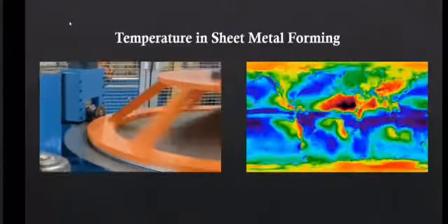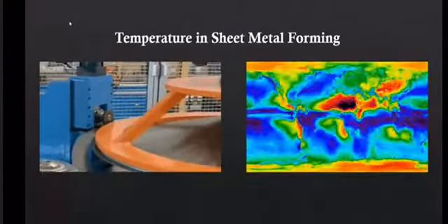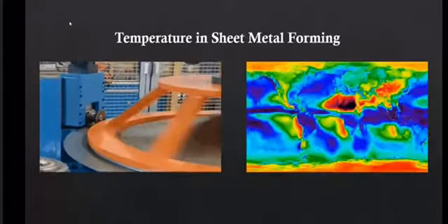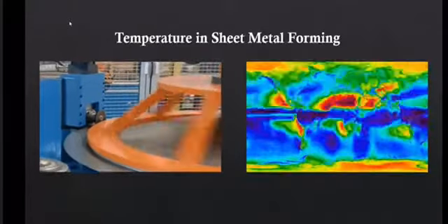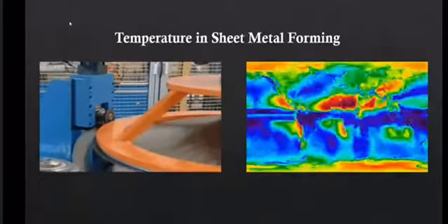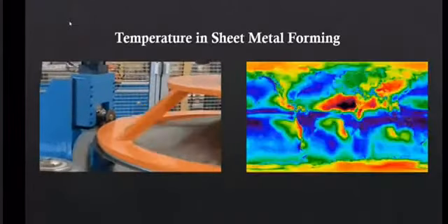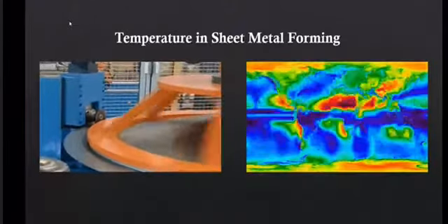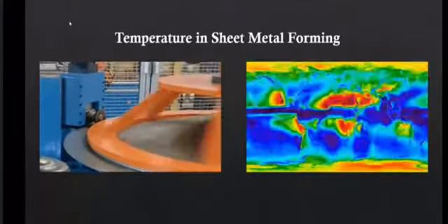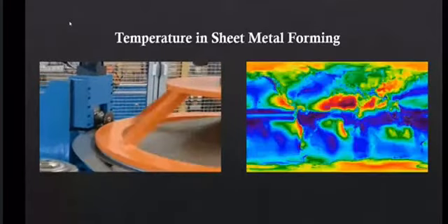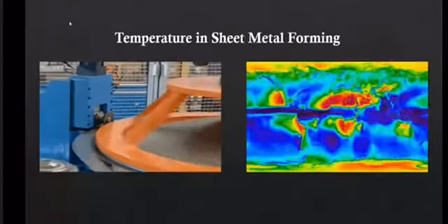There are certain disadvantages or limitations associated with cold forming operations. Higher forces and power are required to perform the operation. Care must be taken to ensure that the surfaces of the starting workpiece are free of scale and dirt. Ductility and strain hardening of the work metal limit the amount of forming that can be done to the part. In some operations, the metal must be annealed in order to allow further deformation to be accomplished. In other cases, the metal is simply not ductile enough to be cold worked.